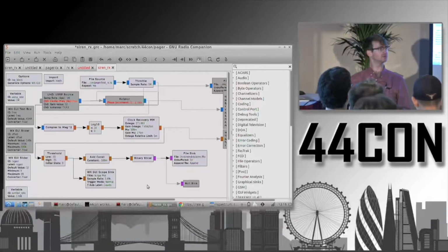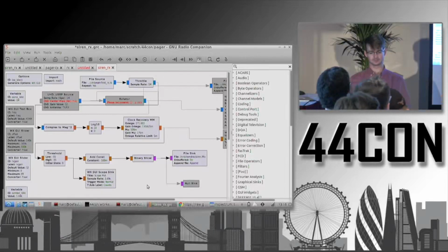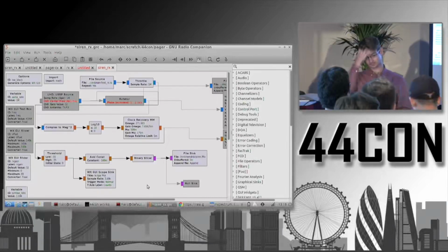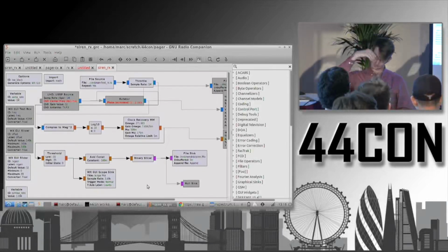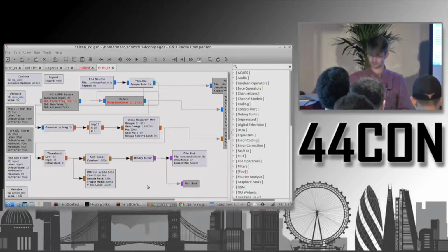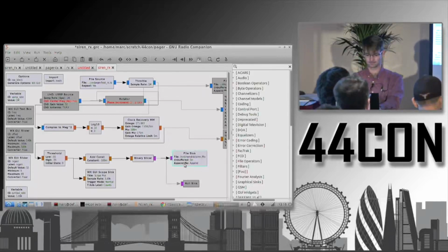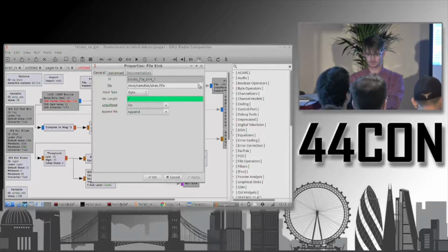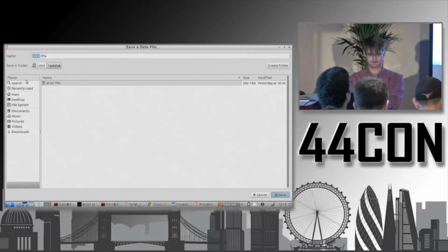And this threshold block is telling us to output a 1 or 0 based on whether it's above or below a certain power level. And again, we're modulating this data. It's amplitude modulation. So if it's above a certain power level, it indicates one value. If it's below that power level, with the radio off, it indicates another value. And so that's just telling us the value at which we say it's a 1 or a 0.